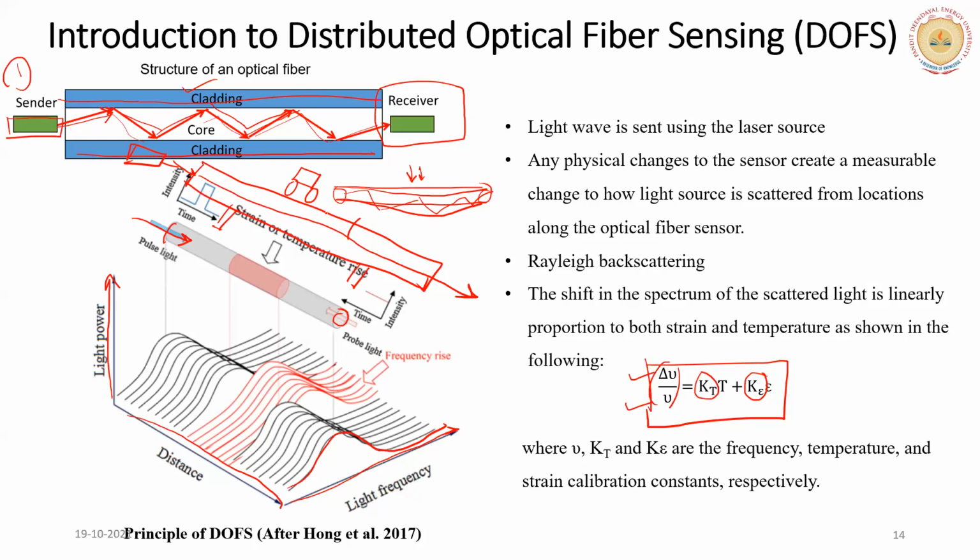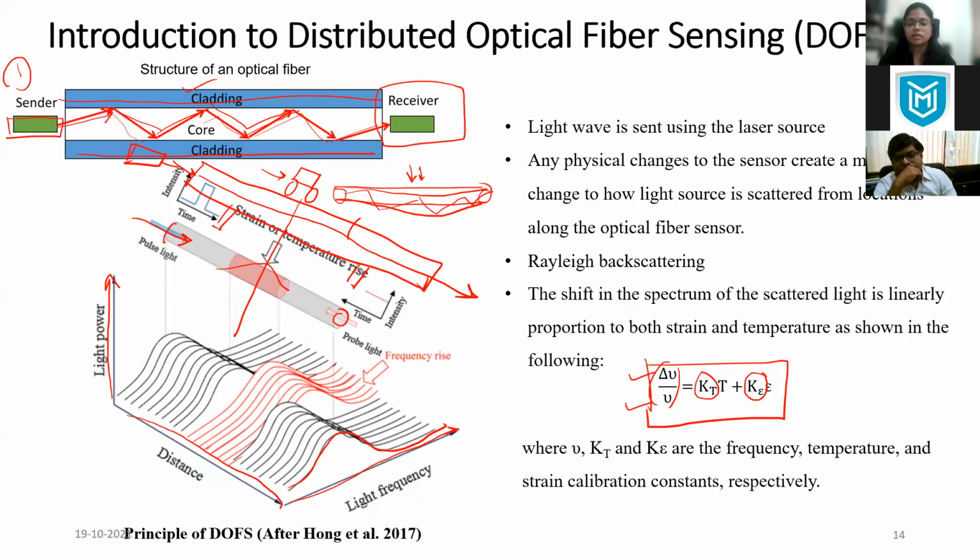This light is sending some signals. In a normal typical case, as soon as a vehicle moves at this point location, there will be a strain developed, and this strain will cause a change in the frequency, and that frequency change can be caught. It can be recorded by our detector, or you can say the receiver end, right? Now in bridges, it is undergoing a lot of dynamic action, right? There will be vehicles moving on and on. So there will always be some strain measured.